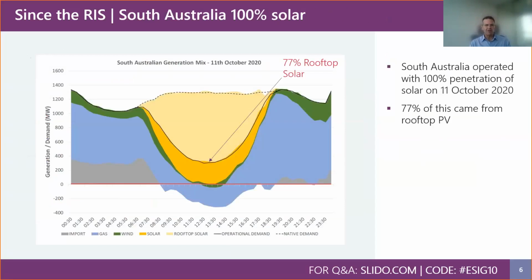I do need to caveat that by saying that we did have 4 gas-fired generators remaining online at minimum dispatch levels to provide the necessary system strength and inertia, but these were not actually required for energy production. Remarkable is also that almost 80% of the electricity demand was provided by the roughly 1.5 gigawatts of rooftop solar installations located in the distribution system of South Australia.